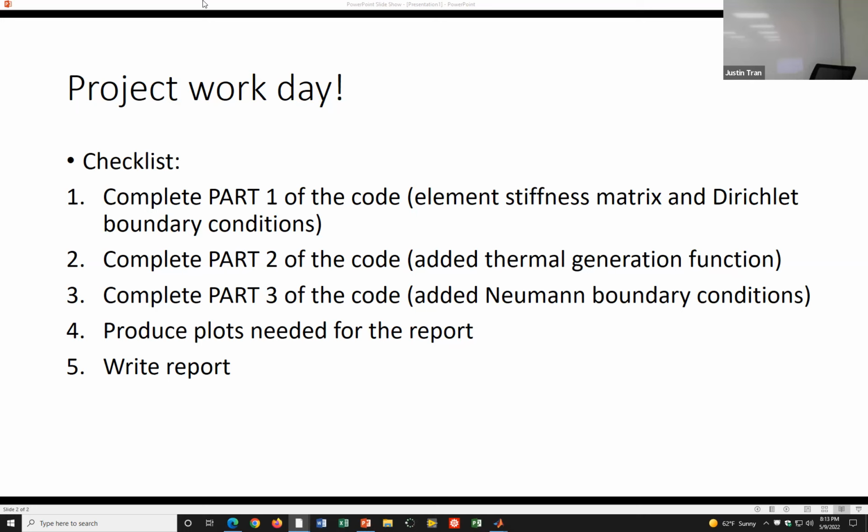And what does it mean by total error? So what it does is it takes your solution and the reference solution, takes the difference of these two per node, and then sums it all up. So 171 is if you add up all the errors. It's just the total difference between this solution and this one per node.